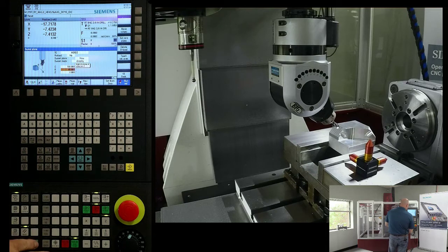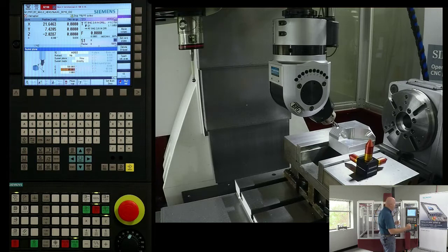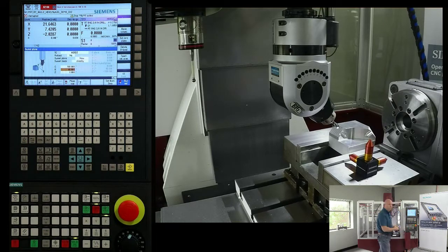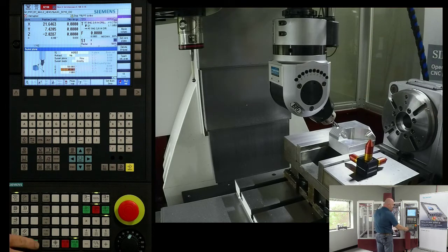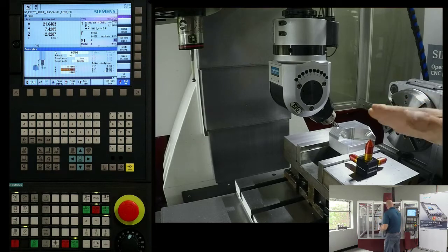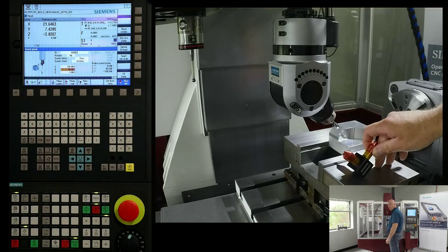So when I hit cycle start, the system is now going to take these two values into account. Now what it prompts me to do, and the way we've set it up, is to work as a manual axis. With a manual axis, the system is going to command me to move the rotaries manually to these axes. So I've already pre-staged it for us. Final cycle start. And now what we've done is we've actually changed the orientation of our coordinate system.